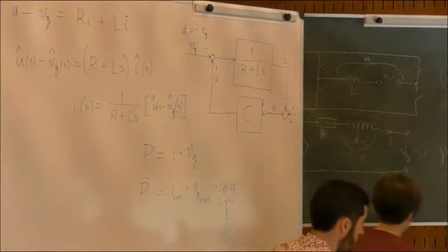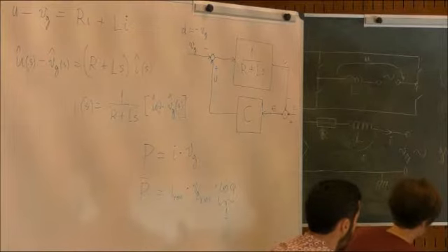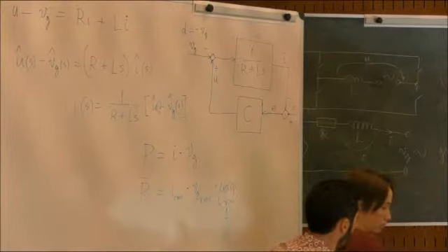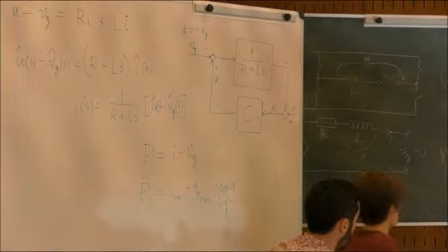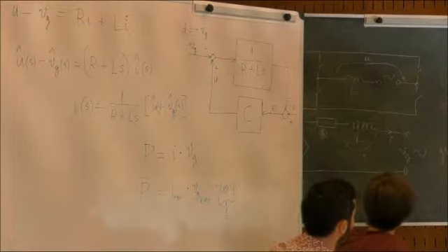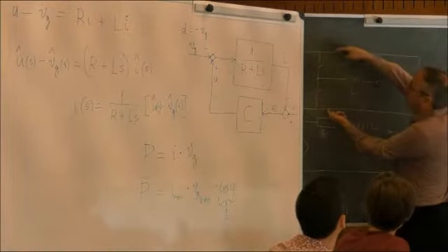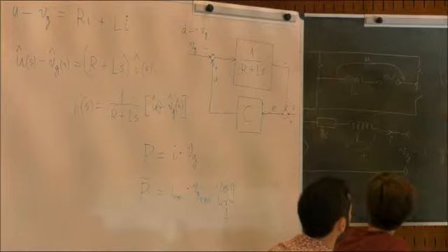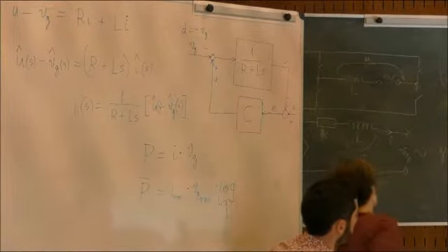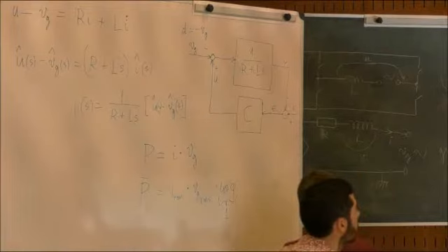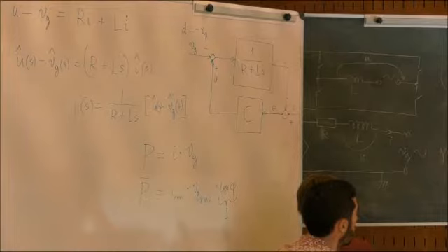And actually it's even more complicated than that, because I do not know exactly how much the solar panels can give. I have to find the maximum point of the solar panels. I have to adjust the voltage here, this voltage on the solar panel. I have to control it so that it reaches the voltage at which the power delivered by the solar panel is maximum.